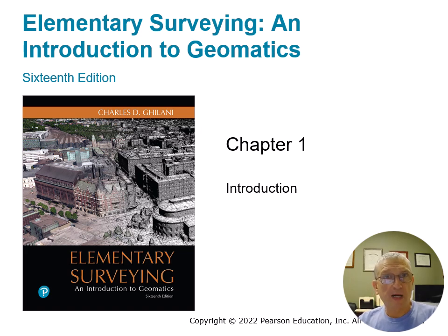Our textbook math problems have always been, turns an angle of 30 degrees. It goes this far, the sine and the cosine. You compute, well, it's not 30 degrees exactly, and even if you use a $30,000 instrument, you're still not going to get exactly 30 degrees. You're going to get really, really, really close, but there is error in every angular and distance measurement made.